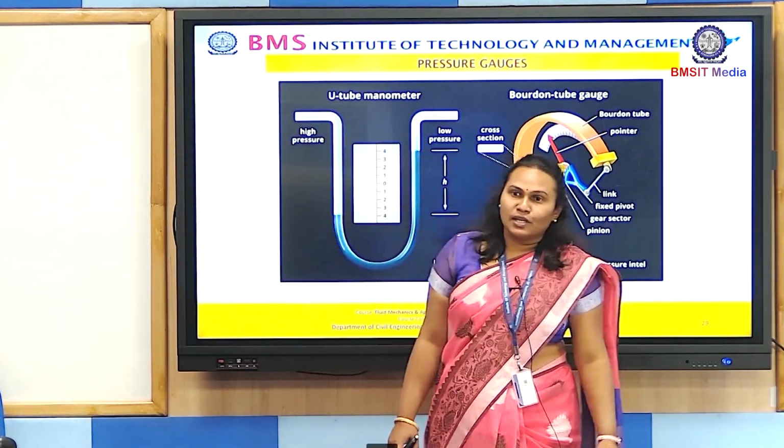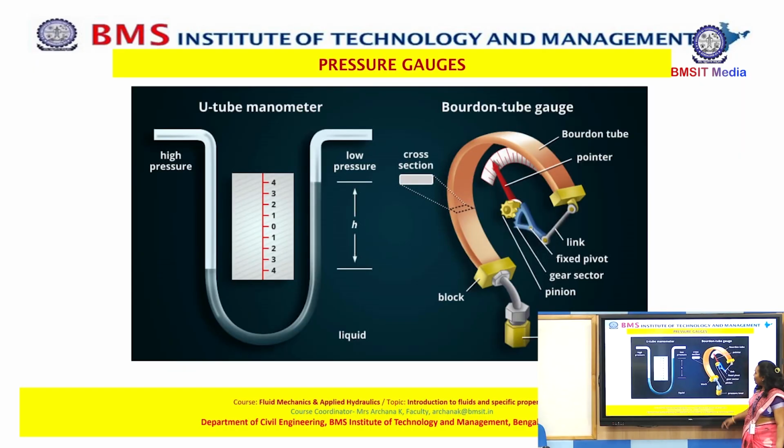This is a mechanical pressure gauge consisting of a small tube known as a Bourdon tube, made of a copper alloy, and this tube is very susceptible to small pressures. The tube can contract and expand depending on the pressure applied, and it is connected to a pressure inlet and a gear mechanism with the needle.